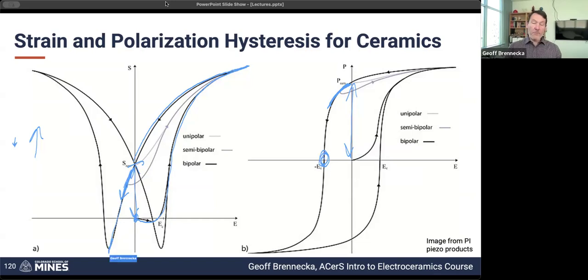So the minimum in the total strain is right here, where we're now pushing against the poling of the material enough that suddenly it starts to switch after all. And so now we're actually switching the polarization of the material. And as we flip the direction of these dipoles, now the additional strain that we add is going to make it continue to grow again.